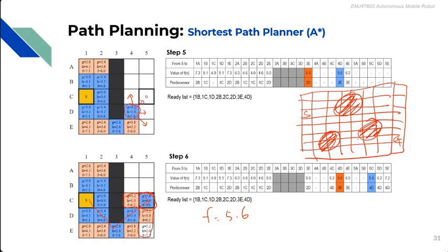If it's like this, then like this, right? You see that the obstacle doesn't cover everything, but it covers a bit of some cells. So you straight away consider that these are the obstacles. Cannot go through. So you see those that intersect, oh, this is the obstacle. This one is the obstacle. So you don't go through this. So later when you expand it using A star or Dijkstra, you should be able to see, oh, probably this is the shortest distance. Or maybe it's going through here. Something like that. Understand?